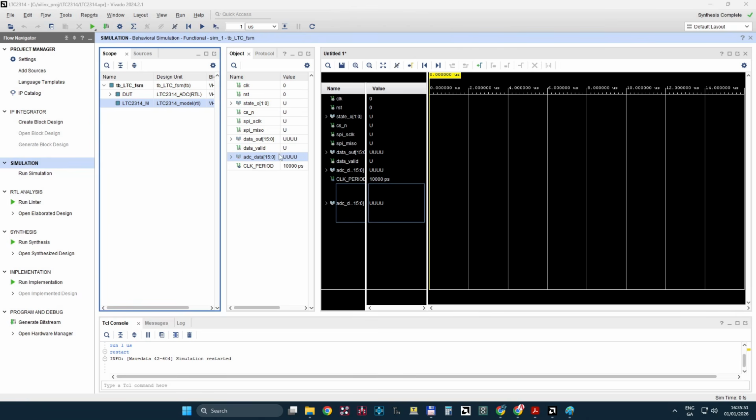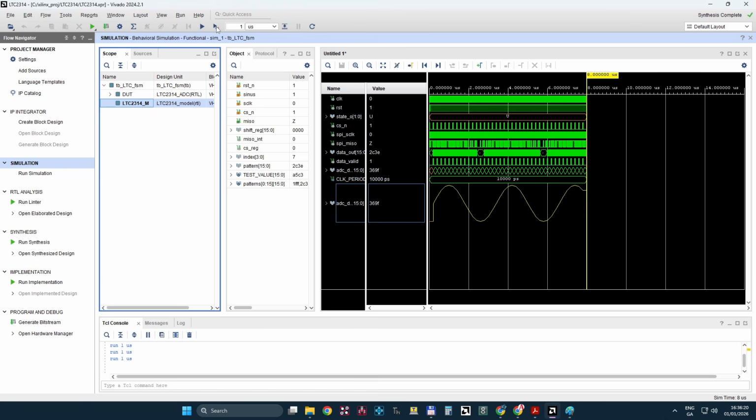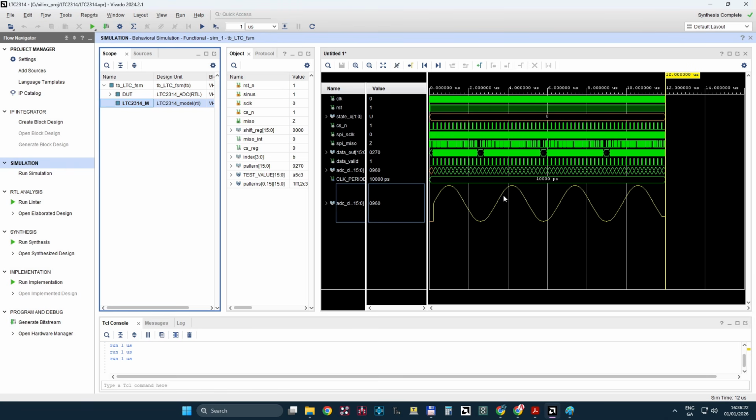Okay, very quick, the simulation. So what do we have here? This is the test bench, which is instantiating our interface, our LTC interface. And this is the model, which is creating, let's say, fake samples like the chip is actually attached. So I'm going to start the simulation, if I remember how. Yeah, here, bam. And I'll go 1 microsecond in steps of 1 microsecond. And you see here a nice waveform is showing up, right?